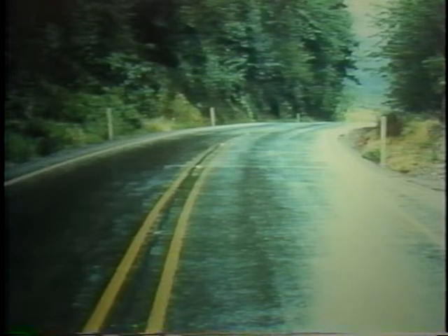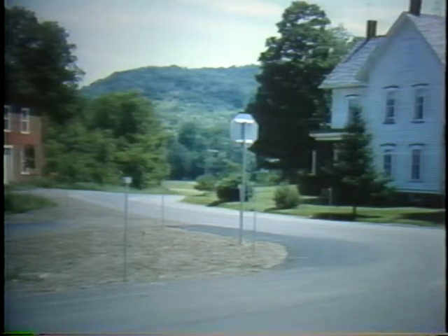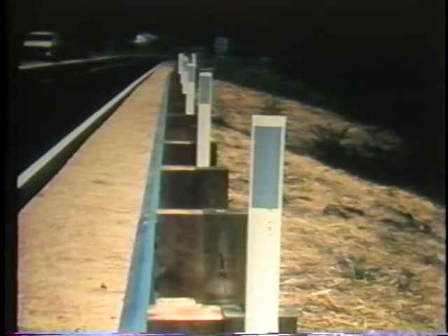Post-mounted delineators are particularly effective in showing the roadway path on combination crest vertical and horizontal curves. If the pavement at intersections is not adequately marked, post-mounted delineators can help. The number of accidents involving barriers could be reduced by placing retroreflectors on them. The retroreflectors should be mounted on the post and not on the face of the rail.